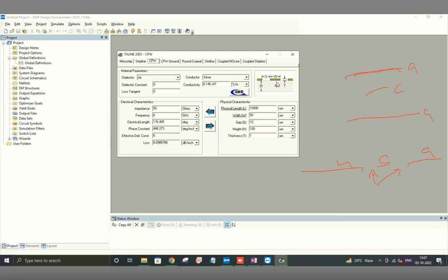Again, I just want to show one thing before we, because we're running out of time. There are some numbers already entered here. I'm just going to run the calculation for that. But all I wanted to point out is that now the effective dielectric constant is no longer the same as what is specified. The reason is now the field lines. So remember that this here is all dielectric. Okay, this has some epsilon r here, but this is air above. And the field lines are going to have both things going from the top and going to the bottom as well. How much of that will depend on what is the dielectric constant, what is the spacing between those plates.